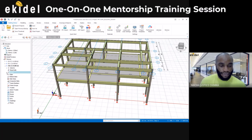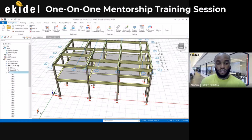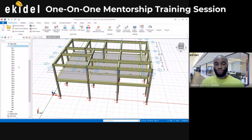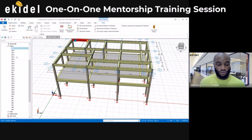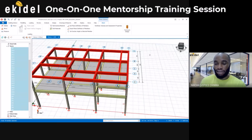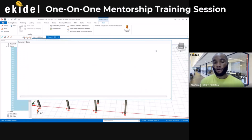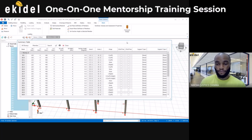Click on beam and then click on this arrow sign here, or just double click on it. It will list down all the beams that you have on story 2. Click on the first one, hold your shift key, and click on the last one. The last one, okay. You see that? You can come and right click now and then say properties. It will display the table of all the beams. Can you see this now?